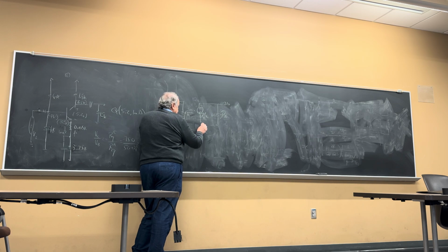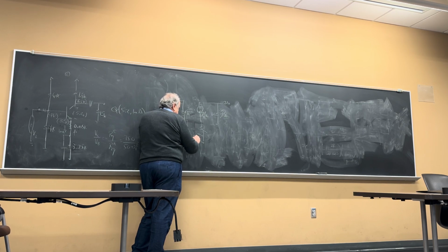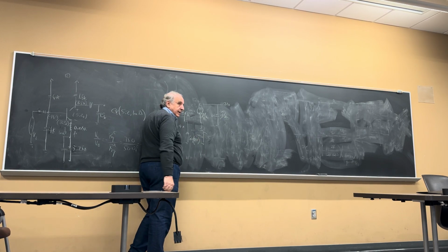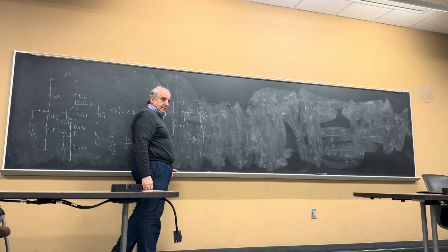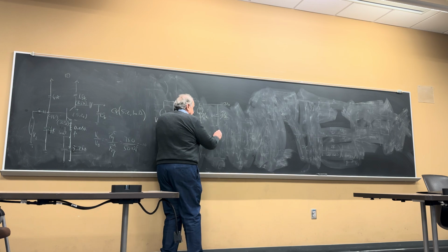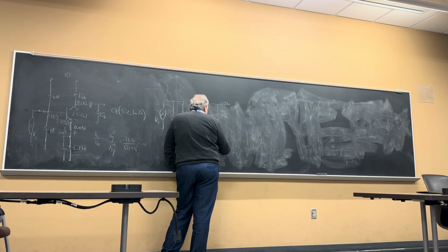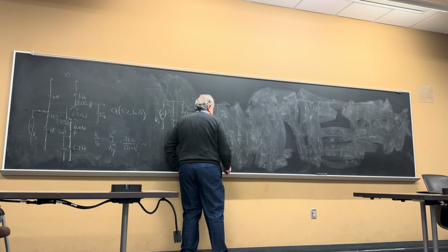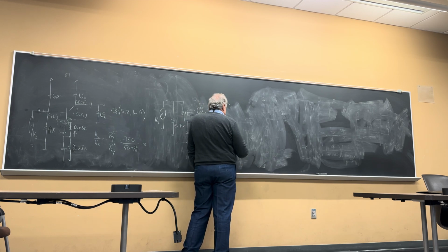You get a resistor here, which doesn't matter. And this resistor will be what? 50 times beta plus 1, right? 50 times beta plus 1. Now, V out over V in is V out over IB times IB over VB.